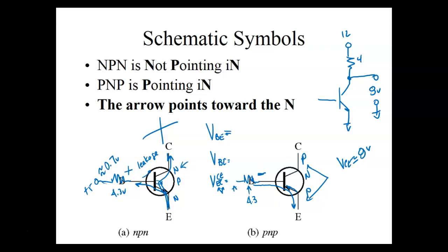And what that's going to be controlled with is base current. So the less base current I put in, the valve closes, which means it lets less current go through. The more base current I put in, the valve opens until we get it wide open. You can't open a water valve more than wide open. So we have two regions we can operate this in. We operate it in what we call saturation.